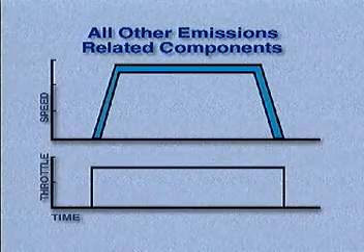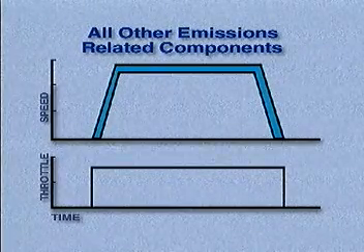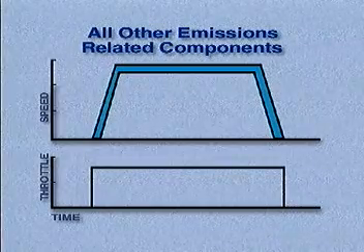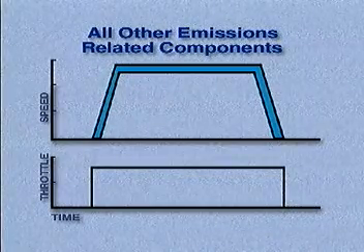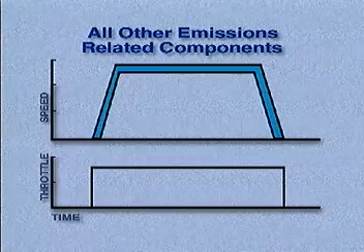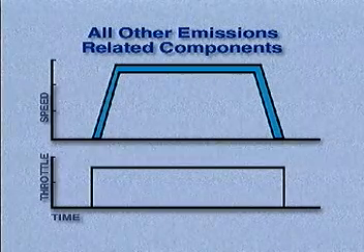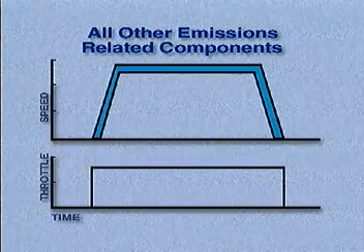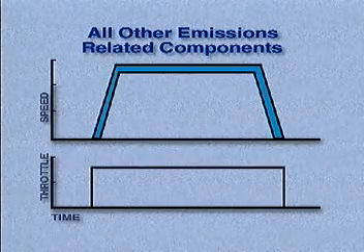In general, if a readiness test is completed and no DTCs are present, and the malfunction indicator lamp does not light, the repair has been successfully completed. If any DTCs are still present, follow the diagnosis and repair procedures in the service manual.